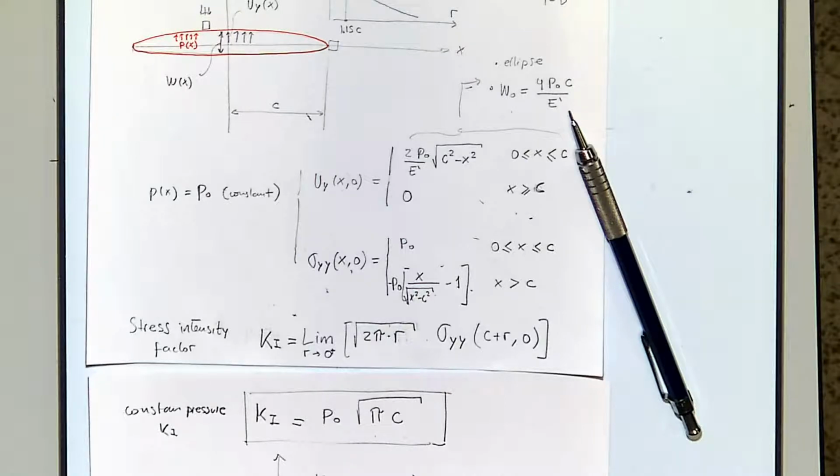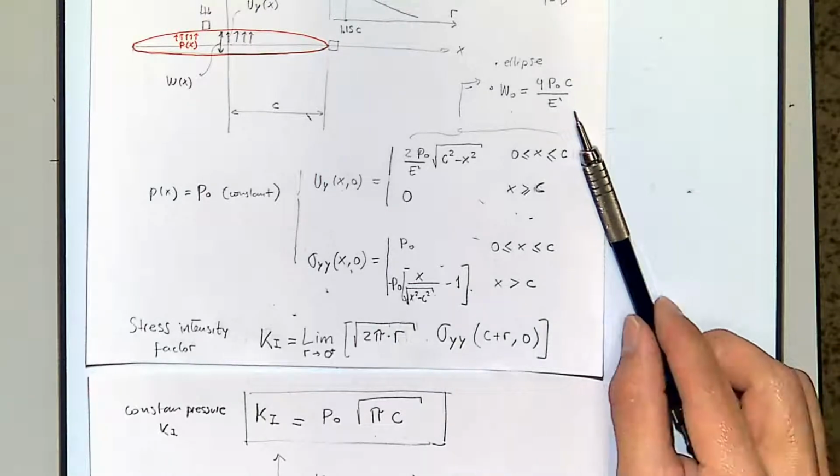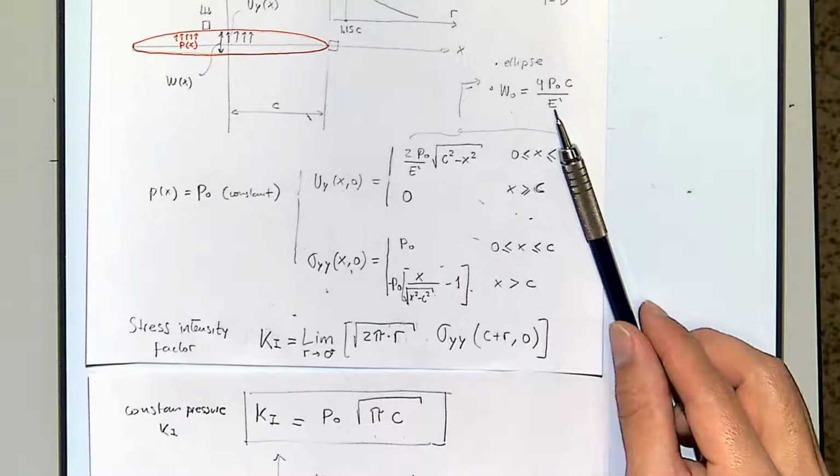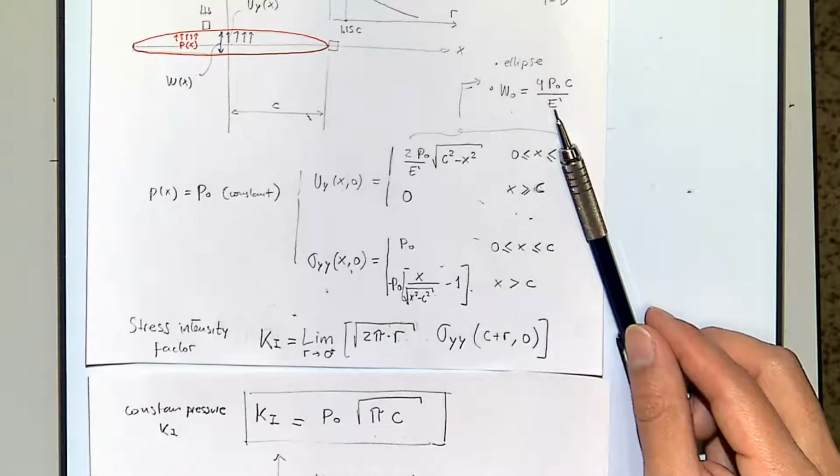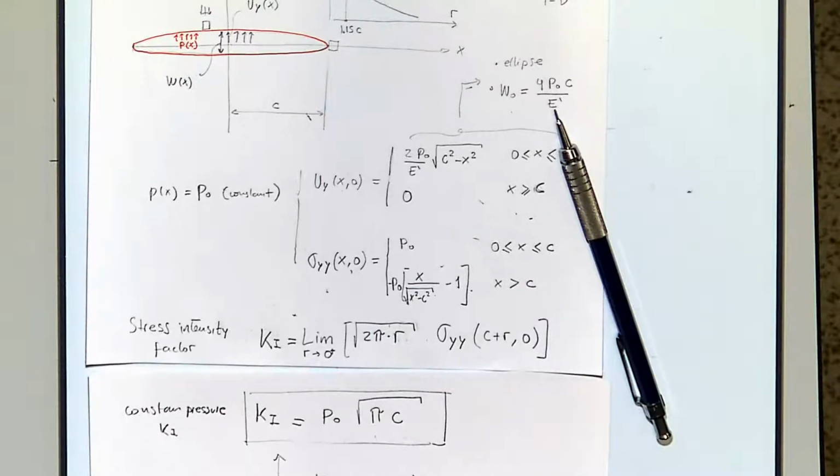A reasonable net pressure is in the order of 1 MPa or a little bit more. Not more than that. 10 MPa maybe is already quite a bit. But just remember, about 1 MPa, okay? What is the Young modulus of a typical rock? How much, Hamza? More than 1 gigapascal. Let's say 1 gigapascal, right?